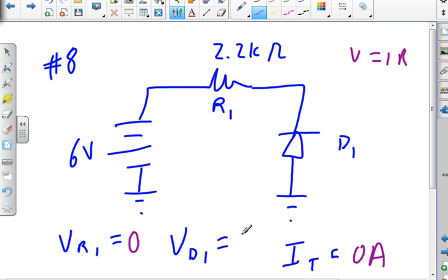Well, that's correct, 6 volts. Guys, Kirchhoff's law says the summation of the voltages on a loop has to be 0. So if I go up 6, I go down nothing, I'm going to have to go down 6 more, right? So we could call it minus 6 volts, depending on how I put my voltmeter, that would be okay, but we couldn't call it 0 volts.